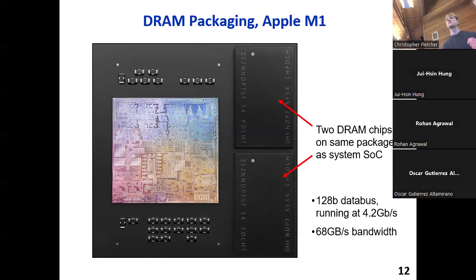Once the DRAM controller sends the signals over to the DRAM that say, open a bank, grab data, despite the DRAM being a passive device, it will do a thing sometime later. That thing might be that the data will appear. So once the DRAM controller initiates an access, even though it's a passive device, as long as you keep it connected to power and you send those commands, just the way it's designed, you're going to get your data out sometime later. And we'll actually see a timing diagram of how that works in a few slides.